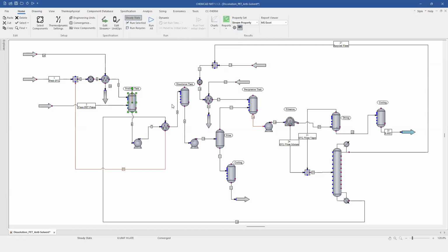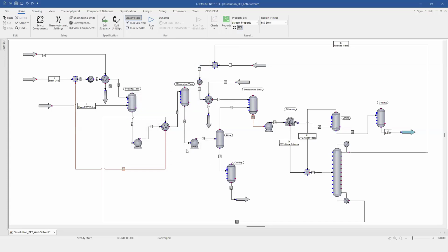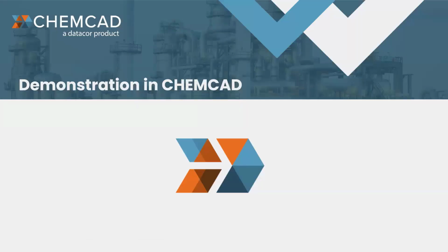In this step, the flakes dissolve in the hot solvent, which selectively dissolves the flakes but leaves behind some impurities like fillers or other polymers. So the product from this step went straight to the first filtration for the PET.